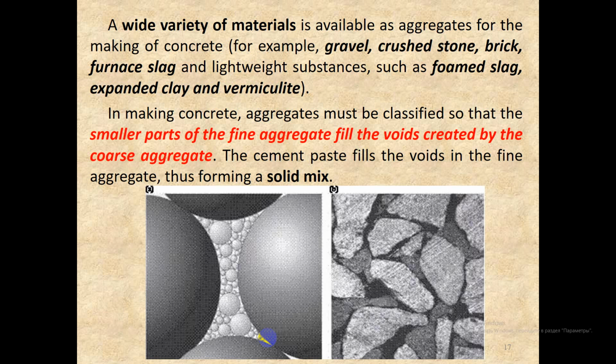Aggregate is usually specified by the maximum size of aggregate included. Most structural concrete is formed using 20 mm aggregate, which means the maximum stone size in the mix should rarely exceed 20 mm. If there are large pours of concrete, larger maximum aggregate sizes are sometimes used.